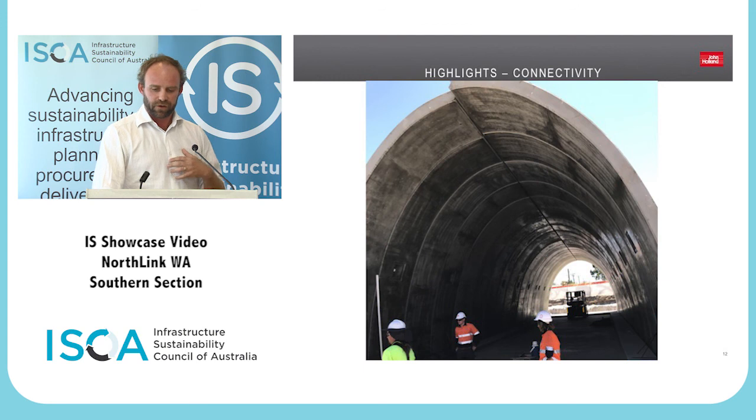What you've got is a very high open structure. It's 5.5 metres high. I think your typical box culvert's about 2.8 metres. And you've got its alignment such that you can see from connecting roads from several hundred metres away right through and out the far end, such that it provides good natural surveillance. Another noteworthy point about this structure is that it's actually leaner than a typical box culvert.